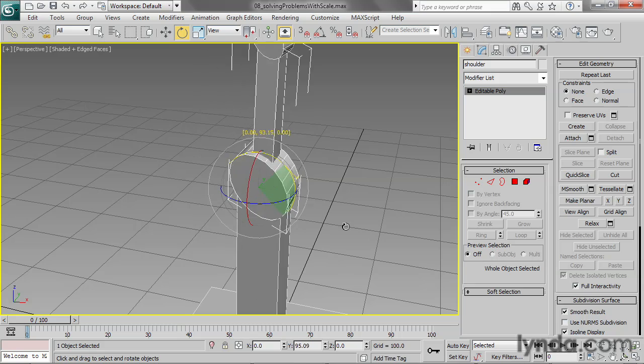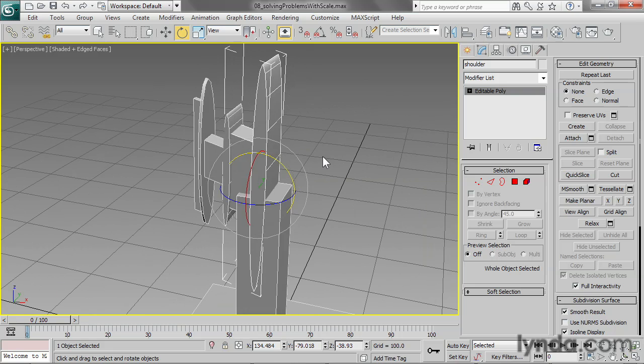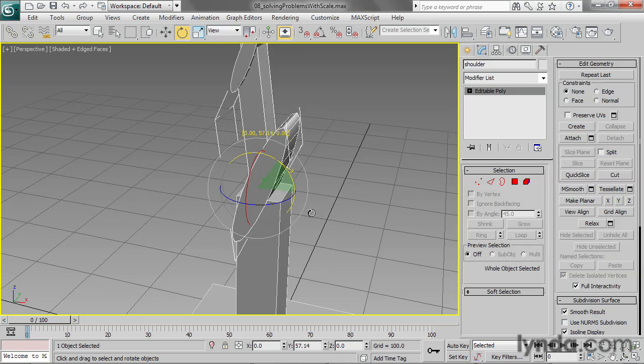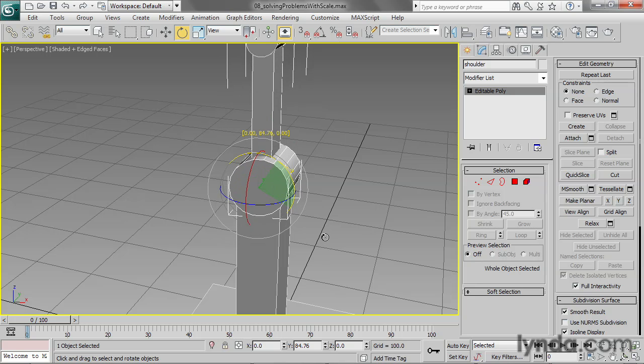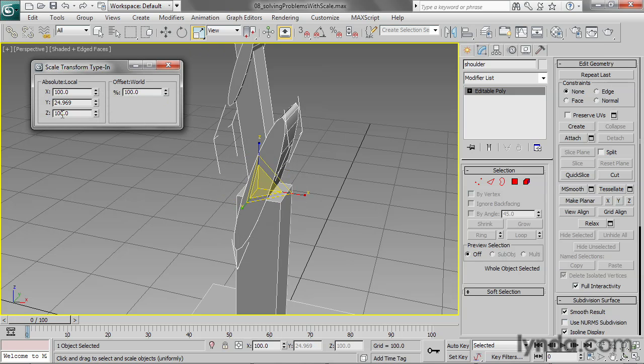And then additionally, 3ds Max has sort of gone behind my back here, and it has applied an inverse scale to this child so that when the rotation value is 0, it looks okay. But that's deceptive. If I have that child object selected and I go to the Scale tool and right-click on it, you'll see that the absolute Y scale is set to 25% or so.